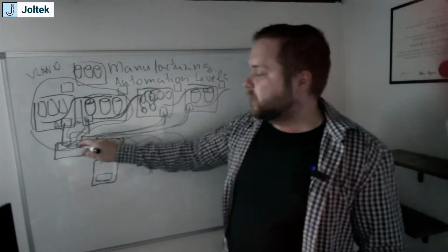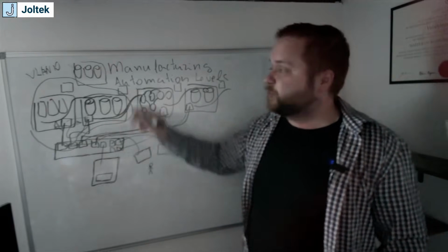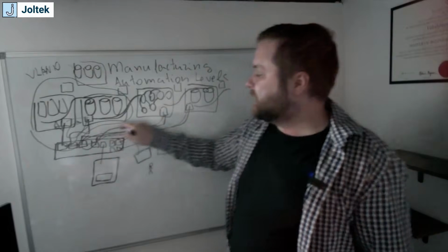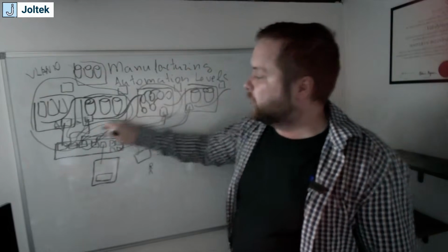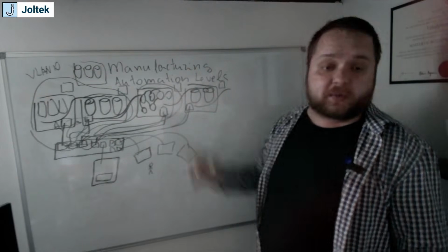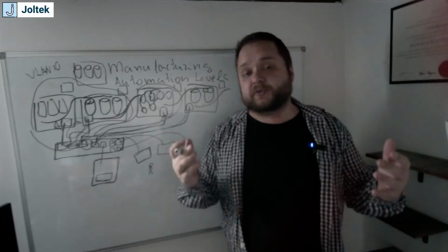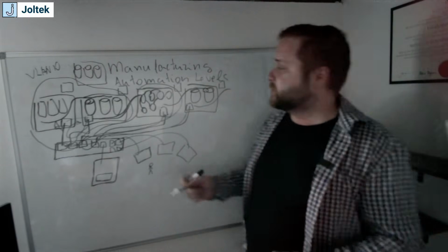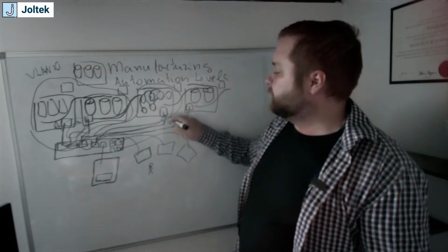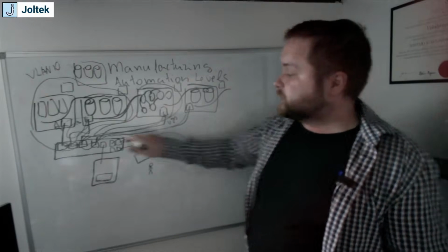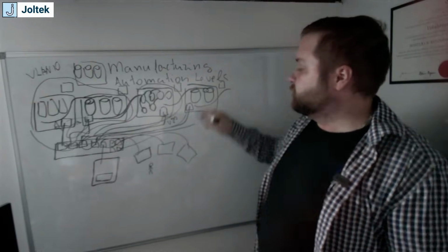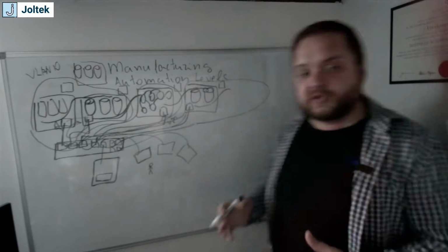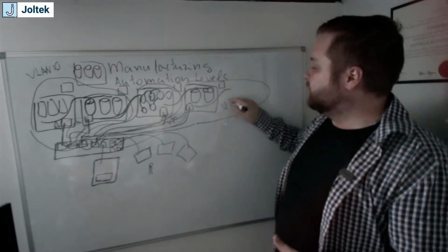But now this switch needs to route between VLAN 10 and whatever other VLAN is available. So here I'm going to create a second VLAN, and this is going to be the process area, right? In certain facilities, process areas are fairly intricate, right? So you're going to have different tanks, different devices, different cells, different vision systems. So this is going to be VLAN 20. And last but not least, you're going to have some kind of packaging area. We talked about just the storage, but here you have palletizing, you have shipping, you have all sorts of different products. And this is going to be VLAN 30.